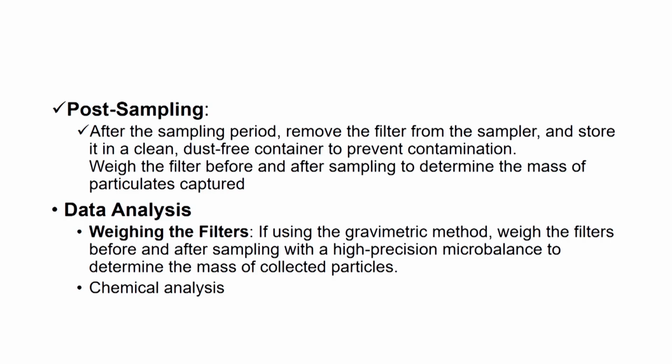So post sampling, after the sampling is completed, the filter that is collected is removed from the sampler and stored in a clean place. This is very important, and you need to have a dust free container to prevent contamination. Dust is highly contaminating, and since dust is in the coarser mode, if you just keep your sample in the open space, dust can be deposited.